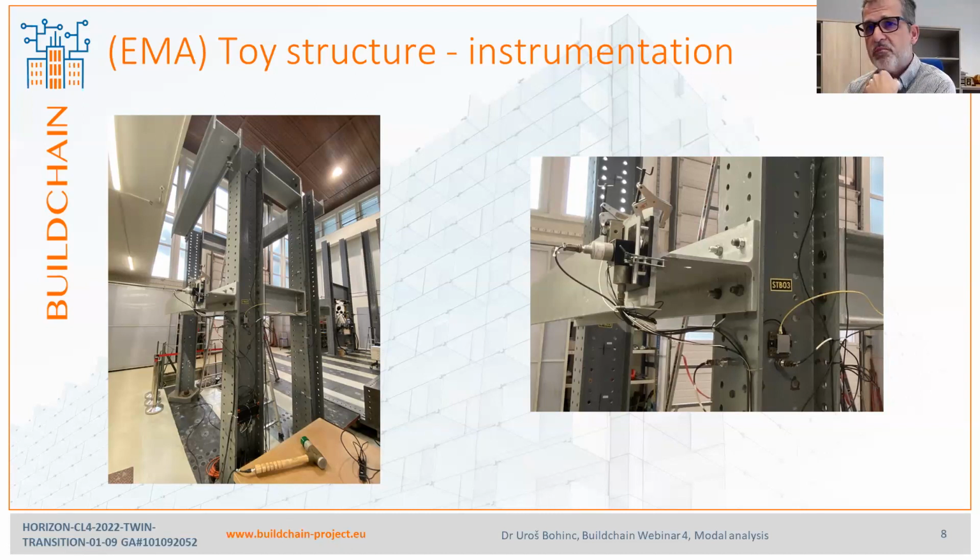So there is a response which can be modeled with a numerical model, and we try to match the results of the numerical model with our experiments. So we used a modal hammer shown here on the left picture at the bottom to excite the structure at different points.